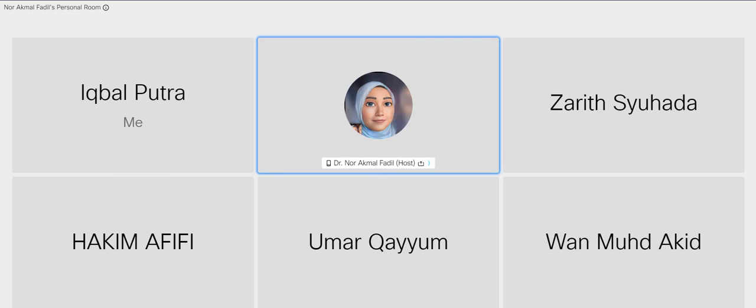And if you think that the engineering component has some load other than static compression load, martensite needs to be tempered so that, of course, the hardness will be reduced, but the toughness will be increased. The brittleness will be reduced. So the explanation must come with justification and must be relevant lah. Janganlah you guna untuk gear, you kata impact load tak important. Memanglah salah. Benda yang very obvious memang akan ada that particular effect, you kena make it make sense lah you punya answer.